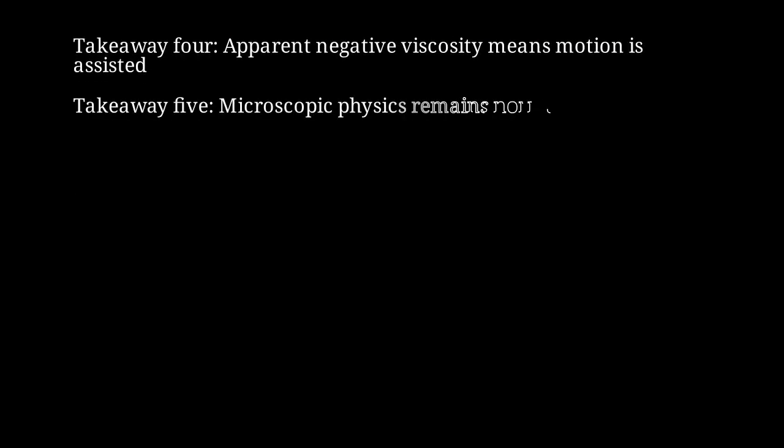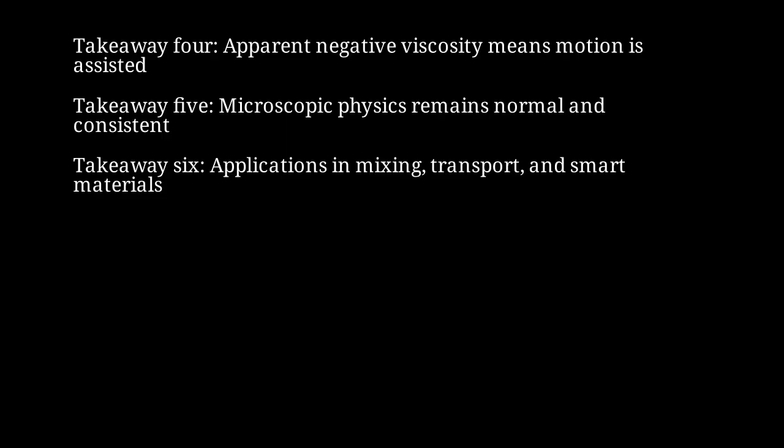This does not violate thermodynamics. The microscopic viscosity remains positive. Energy comes from the fuel. The negative viscosity is a coarse-grained effective property. This phenomenon opens exciting applications in micromixing, reduced drag transport, and self-fluidizing active materials.